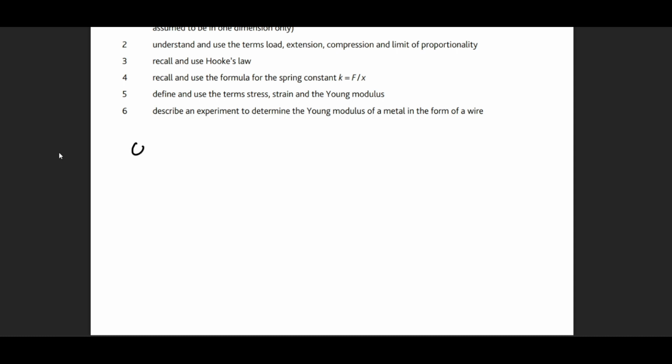Cement that we use for our houses and buildings is a good example of a material that shows compressive strength. You can load up cement with a lot of weight and you can see very tall buildings made out of this material. You can put a lot of weight on this material and it will not shatter, it will not get destroyed in the process. But if you try to pull apart a piece of cement or a cement block, it will immediately turn to dust. So cement is a material that shows compressive strength but not tensile strength.